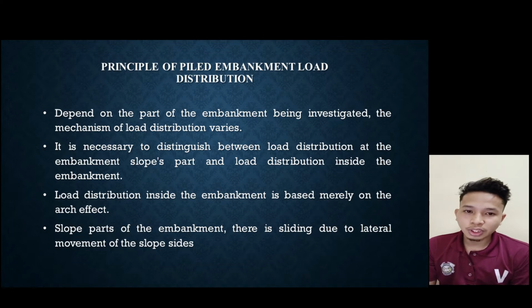Second is the principle of pile embankment load distribution. Depending on the part of the embankment being investigated, the mechanism of load distribution varies. It is necessary to distinguish between load distribution at the embankment slope part and load distribution inside the embankment. Load distribution inside the embankment is based merely on the edge effect, while in the slope parts of the embankment there is sliding due to lateral movement of the slope slide.